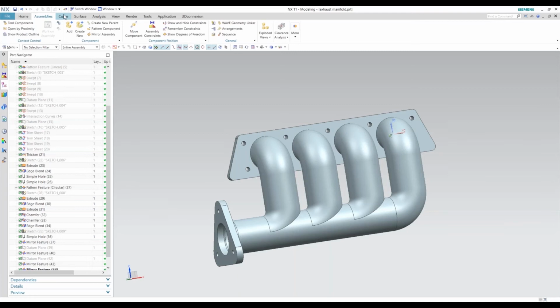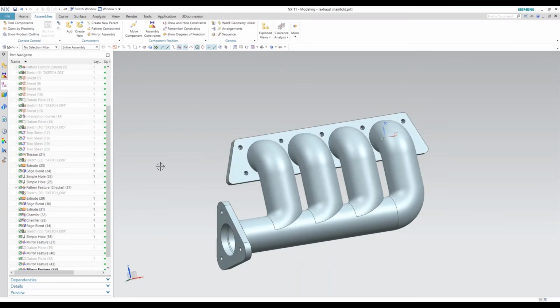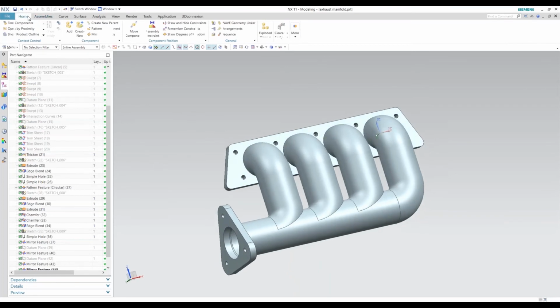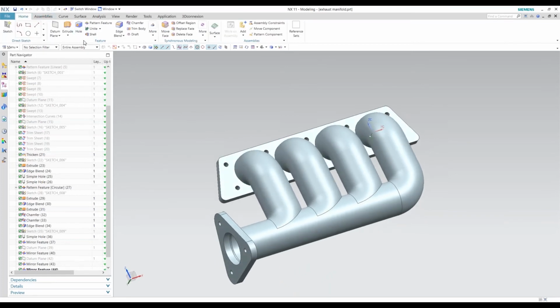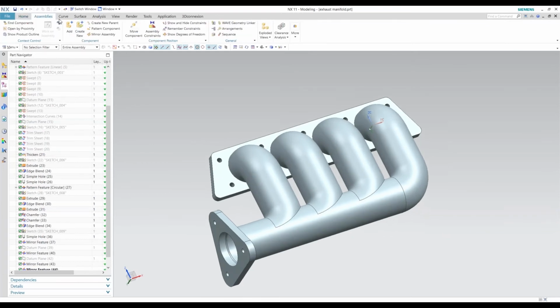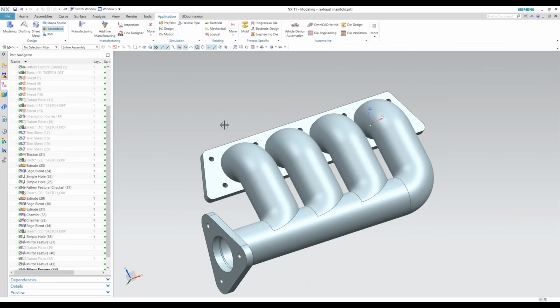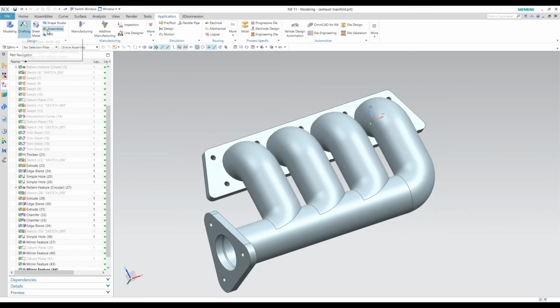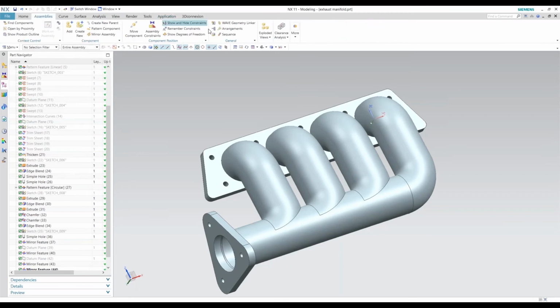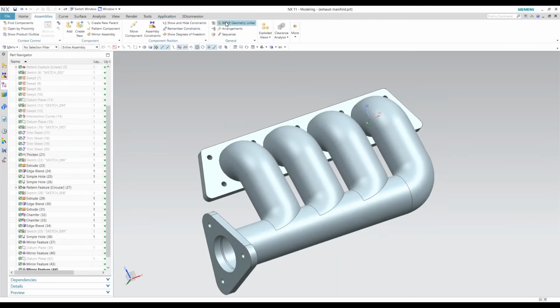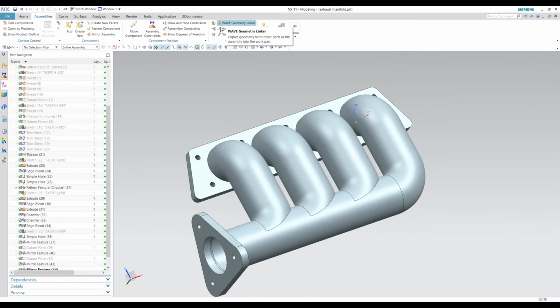You can also have a new part and have all those bodies in there, but you don't want to be doing your analysis on your production parts here. Okay, so to make a copy of this, you want to go to your Assemblies tab. If you don't have an Assemblies tab within your modeling environment, you just go to your Application tab, click Assemblies. Okay. I'll go ahead and do wavelength.